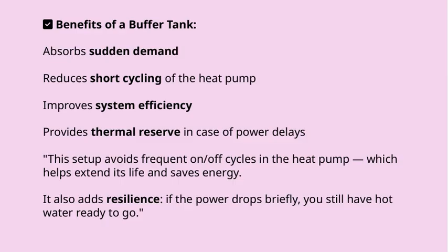Plus, the buffer tank provides a thermal reserve, so if there's a delay in power supply or a brief outage, you still have hot water available. This setup really helps avoid the frequent on-off cycles in the heat pump, which extends its life and conserves energy. And it adds resilience. If the power drops temporarily, you still have hot water ready to go. It's a smart way to make your system more reliable and efficient.